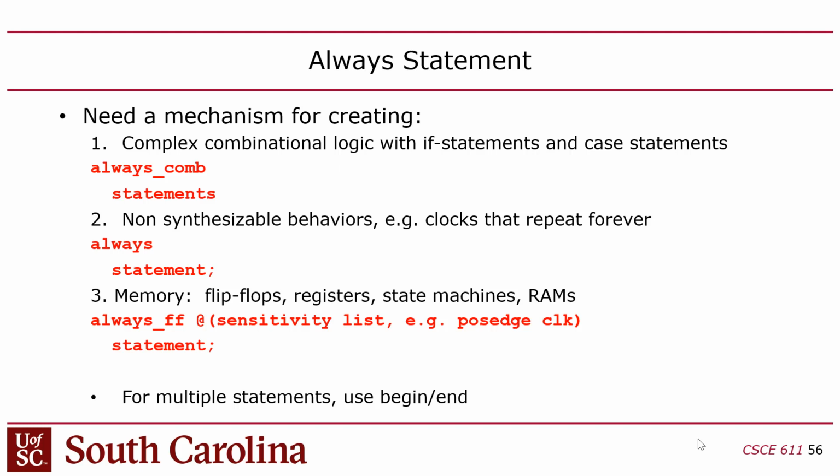The problem is that when you have an edge triggered system, the critical path delay is measured from edge to edge. So you have from the rising clock edge to the rising clock edge. So you get a whole clock period.